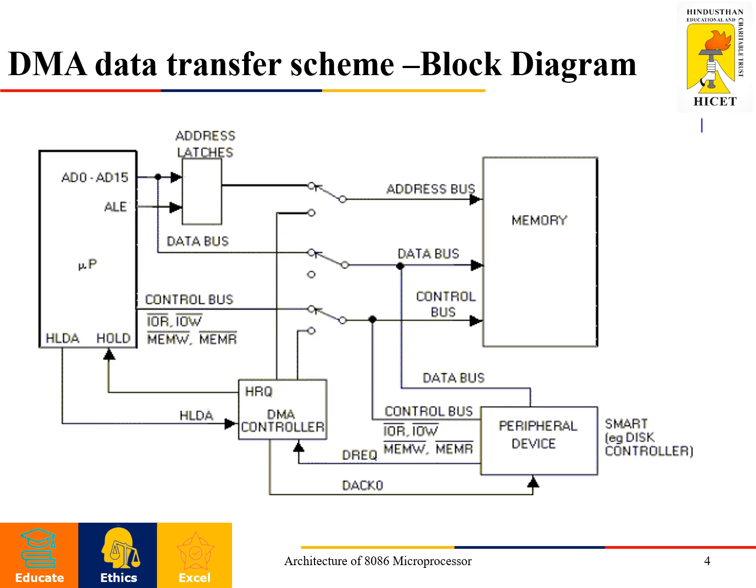Along with this processor, we have latches to temporarily store the values. The address is transferred through these latches and the data is separated from the address-data lines. Now here comes the data bus and here is the address bus. This is the memory. And now the control bus is available. The controls are IOR, IOW, memory read and memory write.